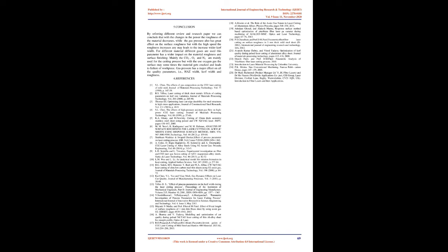Standard roughness Rz increases along with the sheet thickness, but decreases with increase of laser power. By cutting with a laser power of 800 W, standard roughness Rz is 10 µm for a sheet thickness of 1 mm, 20 µm for 3 mm, and 25 µm for 6 mm. The correlation connects the standard roughness, the 10-point height of irregularities, and the mean arithmetic profile deviation. The linear and exponential relationships can be used.